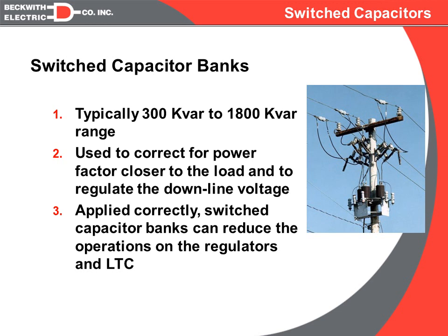As we mentioned earlier, the impedance is typically 3 to 4 times greater reactive than resistive, and therefore reactive or VAR current is going to cause a greater voltage drop. So if we move these capacitors closer to where the motor load is, then that VAR current does not have to flow through as much of the distribution system and therefore does not create as much voltage drop.